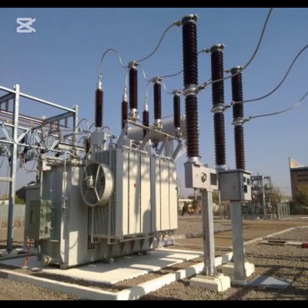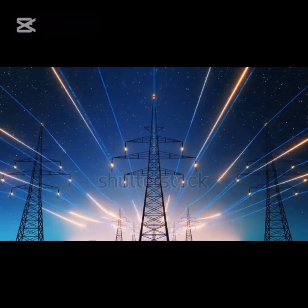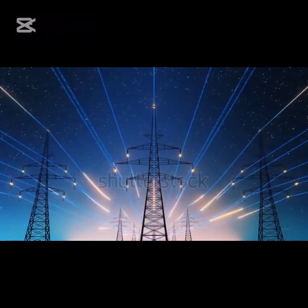Things that change when a transformer is transforming: 1. Voltage level. The voltage can either be stepped up or stepped down. 2. Current level. When the voltage is transformed, the current changes inversely. 3. Turns ratio. The number of turns in the primary coil compared to the secondary coil dictates how much the voltage changes. 4. Load conditions. The output voltage and current can vary based on the load connected to the secondary coil. Transformers are fantastic tools that help ensure electricity can be used safely and efficiently at various levels.